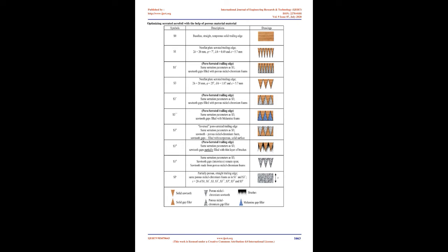As per Howe's theory, the angle between the sawtooth serration must be less than 45 degrees to reduce the noise at the trailing edge. Technique for noise control by surface pressure. Airfoil self-noise is produced due to the interaction of unsteady flow in the form of fluid turbulence with the surface of the airfoil. There are a variety of specific noise generating components attached to the airfoil. The physical process of TE noise was described by Roger and Moreau. For the reduction of TE noise, many passive airfoil noise control methods have been developed, as described in the given table.